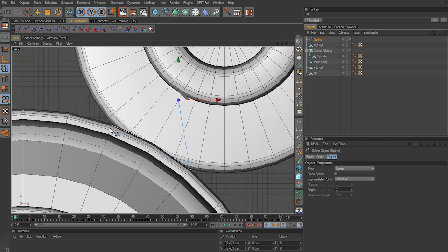And then click back to here. And that's going to close our spline for us. Now, if the spline handles get in the way, you can hit Alt-D. That will move those handles out of the way, and now you can see exactly where you're drawing your spline. Sometimes those handles will get in the way, so you'll need to hit Alt-D in order to remove them.